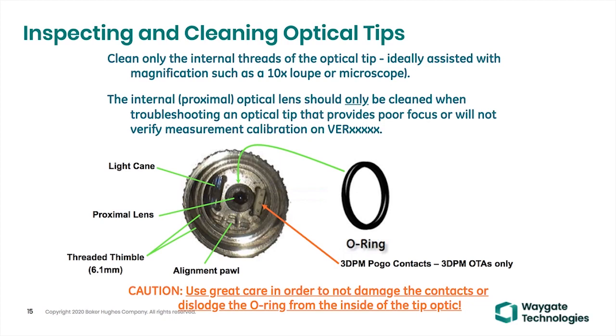If you feel kinks and dents, it could be that your insertion tube's leak tightness has been degraded from damage to the insertion tube. A similar kind of thing can happen out on the bending neck, and it's harder to tell. If there's no damage on the bending neck, usually, Raphael, the Viton sleeve inside is not damaged, unless it's been exposed to some chemicals that have caused it to degrade, and you wouldn't be able to see that.